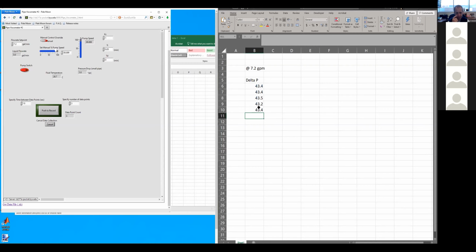Okay, so what would you report then? What's the first thing you would do now? I've got 5 independent samples. What are you going to report as the delta P at 7.2 gallons per minute based on your 5 experiments? This is not a trick question. You just report the average? Yeah, so I'm going to report an average. But the bigger question is, what am I going to report as the error?